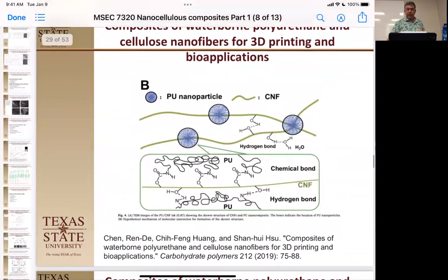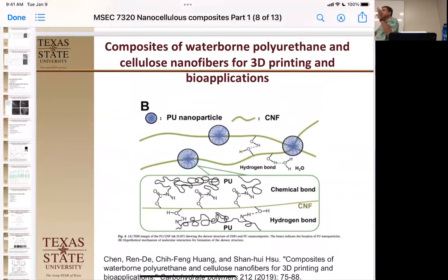So what they think is happening, why there are those little sphere-like things here, is that the polyurethane is actually growing a nanocrystal off of the fibers, off of the hydroxyls of the fibers. Okay, I've seen this behavior in cyanates, cyanate esters. Those do this kind of behavior. Well, they'll grow out in spherical nature if they're constrained. I have not seen it in polyurethane, especially a really plasticky polyurethane.